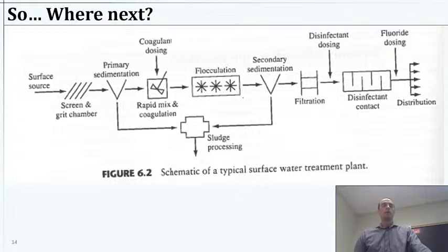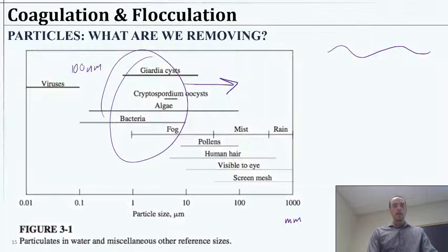From there, we're going to get into flocculation, which is essentially, once we cause the particles to stick together, they do so in a sort of first order reaction in a chamber that we give them, typically a CSTR. We can consider what dimensions of a chamber we need to give them the proper capacity to clump together, and how big those particles are going to be at the end of whatever time we give them. So that's what we're going to work on today.